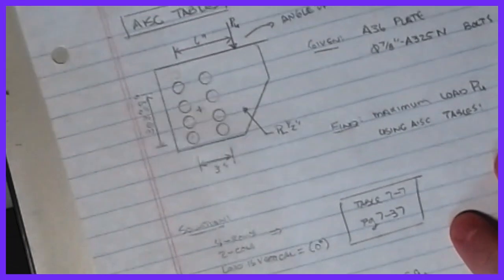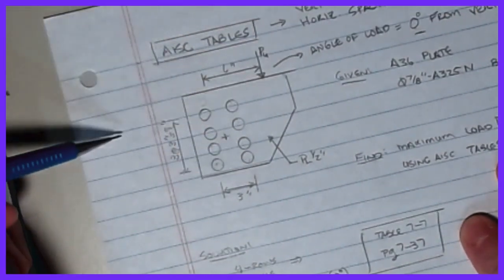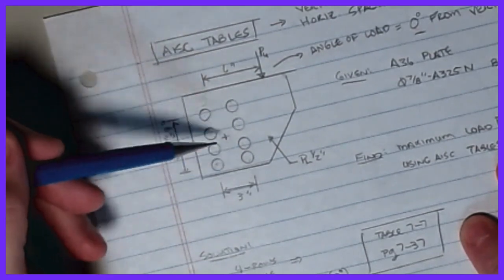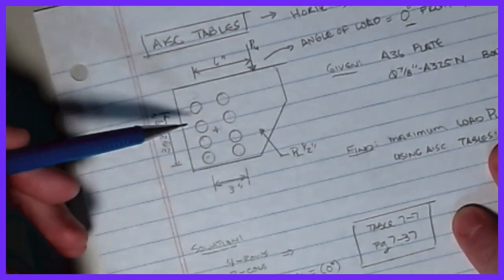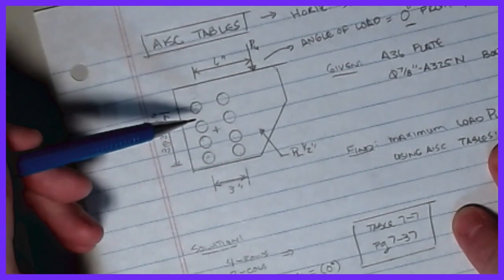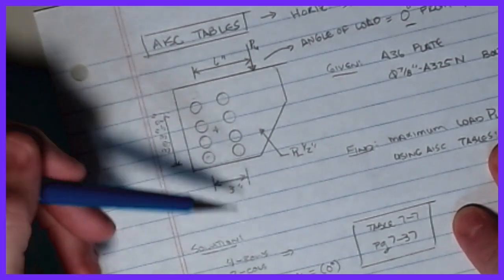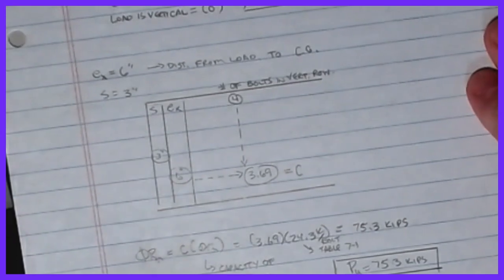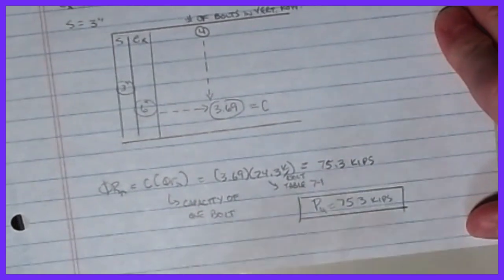But if we go back to our bolt pattern and come up with an irregular pattern, maybe this one bolt is off for some reason, or you're adding on to an existing connection, there's a whole slew of reasons why the arrangement might be different. Then you need another method in your pocket, such as the elastic vector method, or a spreadsheet that helps with those calculations. That's why I like to present both methodologies. But when things are regular, AISC is like a 2-line problem, really. I write down my assumptions, find the right table, pull off C, and boom, we're done.